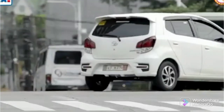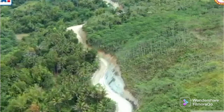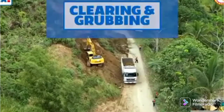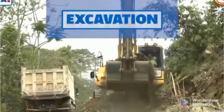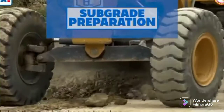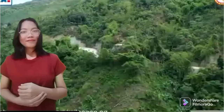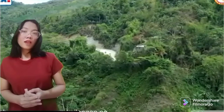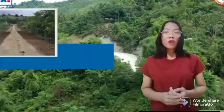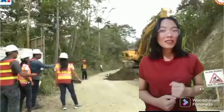Come along to the third step of road construction, which is earthworks. Before roads become concrete and used, there are a lot of processes that it should take. From planning and setting out, here comes the earthworks, which is the clearing and grubbing, excavation, embankment if needed, or simply transferring or putting the soil, cutting and filling, up until the subgrade preparation of the road. Earthworks depends on the landform, if it's plain, mountainous, or a road already. That's why engineers are very important at these steps.